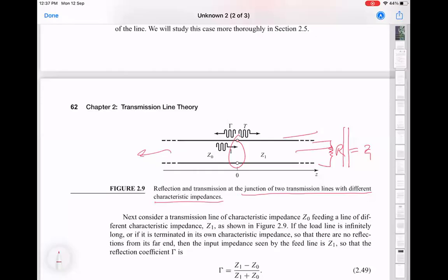One other point before you continue this discussion: in practice, the infinite nature of that transmission line is not important. It is equivalent to a situation where the time over which you are interested, in your experiment or analysis, is long enough that the time for the wave to travel here and come back is shorter than that time.